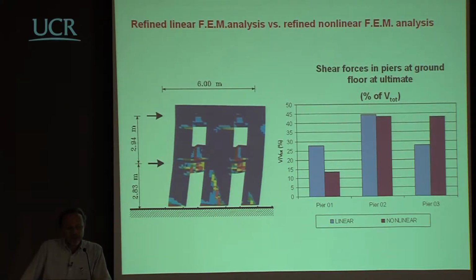There is one aspect which is interesting and related to this kind of response of a masonry wall. What would you guess in terms of possible shear cracking in these three walls? Well, when you are pushing in this direction, there is no doubt that you are going to have a crack in this way, and this way, and this way, and so on. But the point is, in the two outer walls, would you imagine a crack pointing in this direction and this direction, or in the other direction, when you excite the building with a real accelerogram, so that the force will be cycling in both directions?